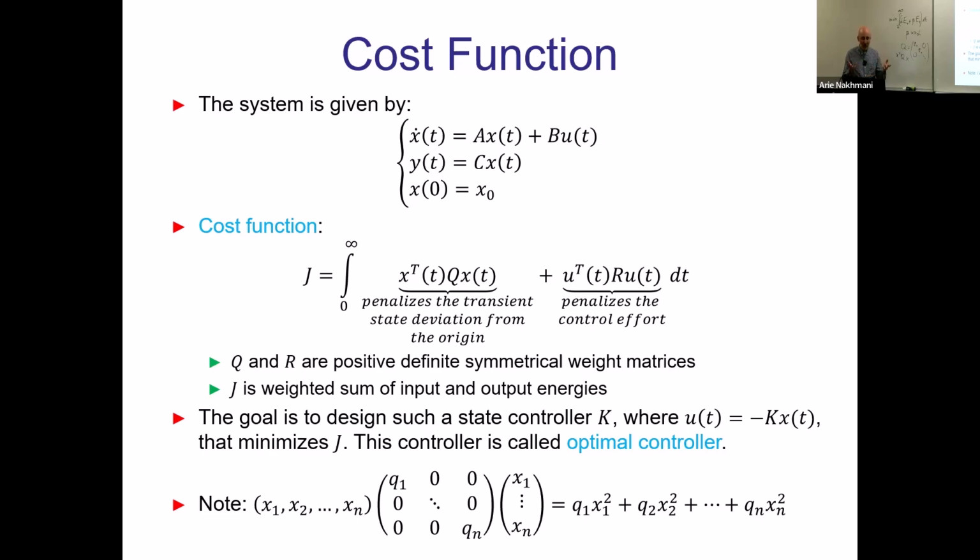Now, you will need to play with these numbers in matrix Q and matrix R to get the benefits of both worlds, practically. So if your u is too strong, too high, increase R a little bit until you get it in the right range. And then this is the best you could get for your x, for your state. So this is the optimal solution.